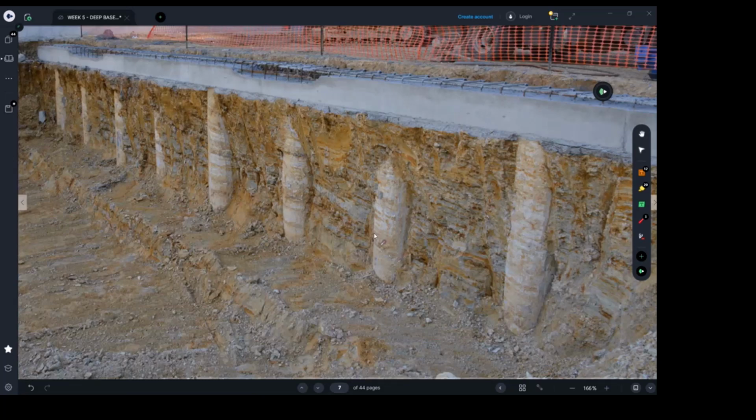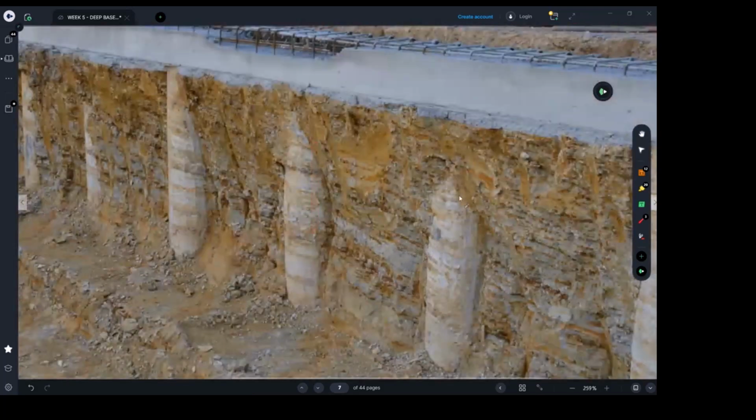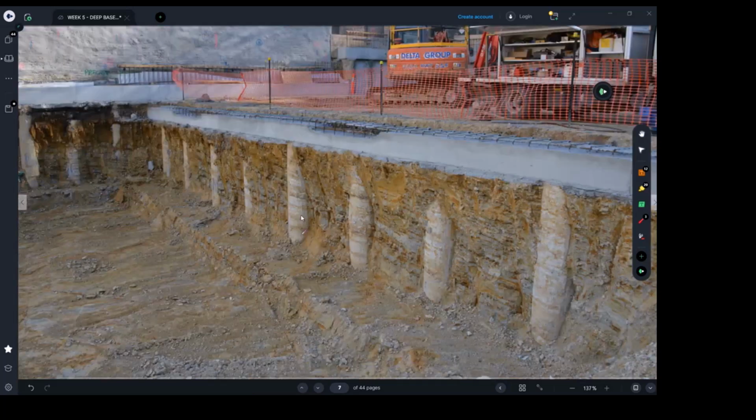That's where you can make more and more money and save more and more time. So you don't need to put in this side 25 piles. You may end up putting only 18 piles. That's cost, that's time, etc. So yes, the soil report may advise us on day one, you put the piles no more than 1.5 spacing. That's what the structural engineer is going to design, and that's what you're going to aim for. But as you excavate, you will find things are actually different. Sometimes builders will do more checks on site just to make sure they actually need to do it.